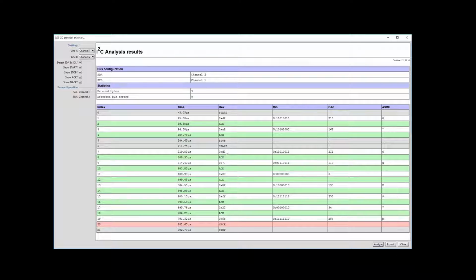105 decimal, and the slave sends an ACK. Then we're going to tell the slave we're interested in register A8. Well, it's not register A8 really, it's register 28 actually, with the uppermost bit set. This uppermost bit, bit 7, signifies whether the address is auto-incremented. Then we're going to send an ACK. The master will send a stop. Master will send a start. Now he's going to read from device 105. That's why this bit is set.